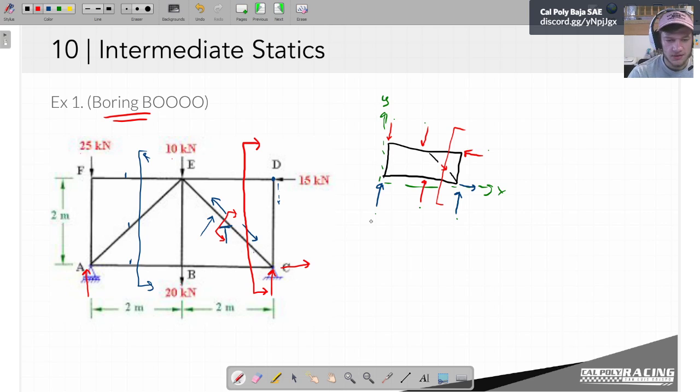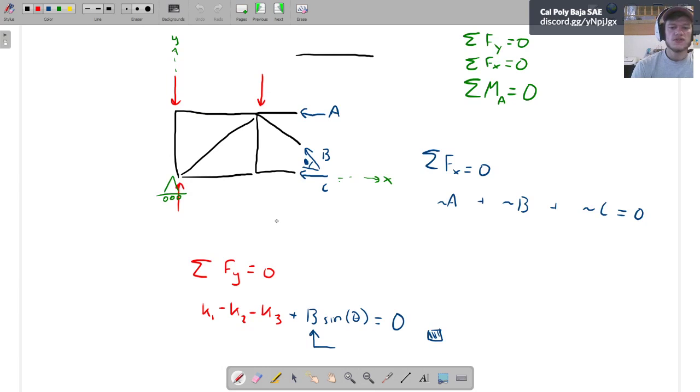So the last big thing to watch out for when you're doing the method of sections is you only have 3 equations to play with. So in theory, you can make your cut whatever shape you want. So I could actually make my cut look like this, right? And I could do that to do method of sections for either this beam here or that beam there. Right? I enter the body and then I leave the body. So I'm never stuck inside. I'm never having to figure out internal forces. I turn what were internal forces into external forces.